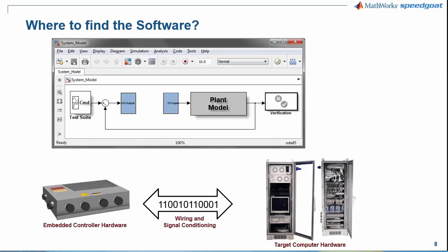Now the HIL simulation is up and running. As you can imagine, there are several benefits of a testing approach like this. It is possible to test your algorithm in a safe lab environment with 100% repetition accuracy. By doing that, you can easily automate testing and reuse the test vectors from the simulation. With this approach, functional equivalence from the simulation to the deployed algorithm on the production hardware can be proven.